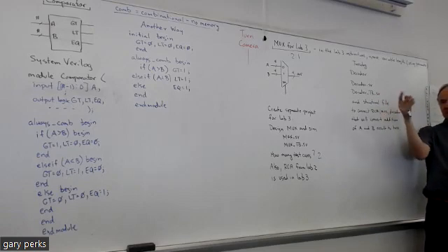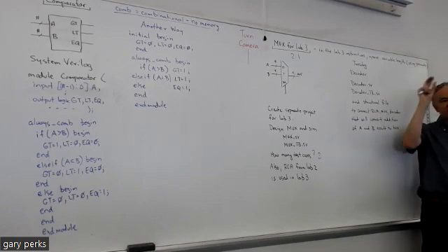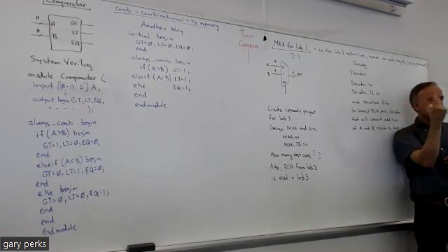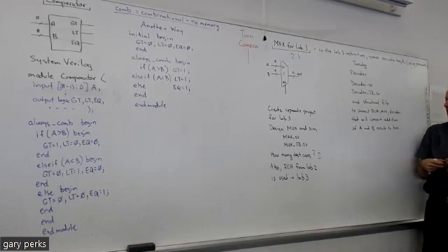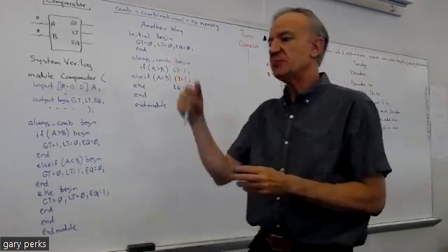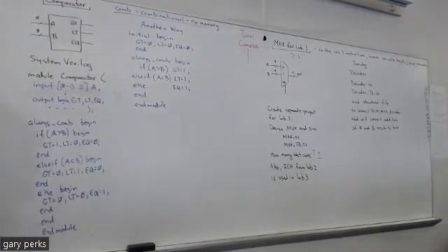The actual structural diagram is on Canvas. Start with the lab 3 instructions. So you'll need a structural file, just like you had the RCA file. And what this circuit will do is that it will add A and B like you did in lab 2, but it will display the result on a 7-segment display as a hex character.